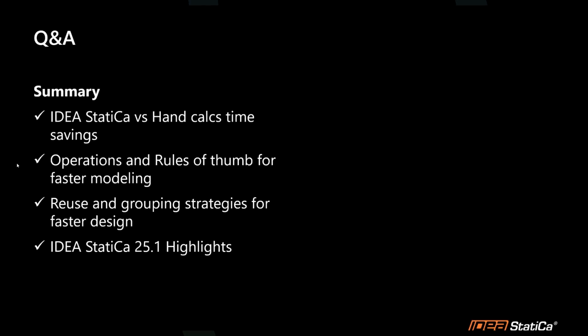There was a question about light gauge and if we can use light gauge within the software. Johan, do you want to take that one in terms of looking at light gauge steel in the software or cold form steel? Right. So in IDEA StatiCa, you are able to model light gauge shapes or cold form rolled shapes in IDEA StatiCa. We do not provide the specific checks for cold form, but we have had some users previously who use the software just to check for the stresses and verify their analysis.